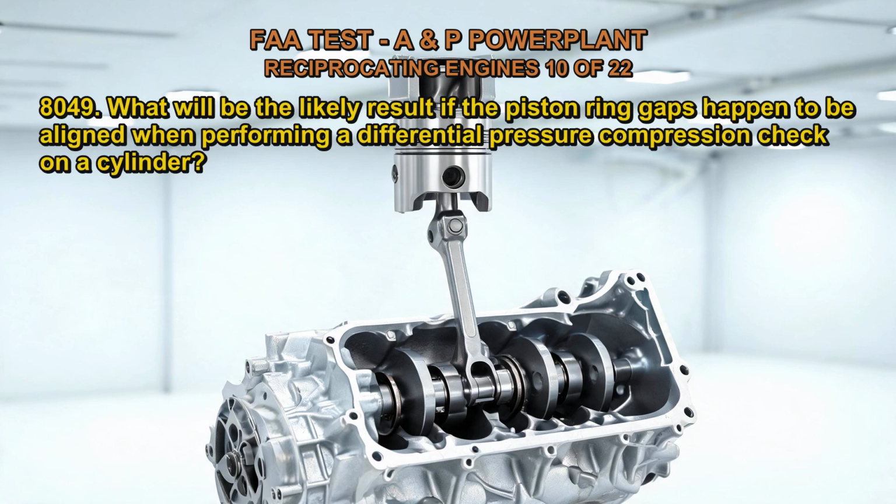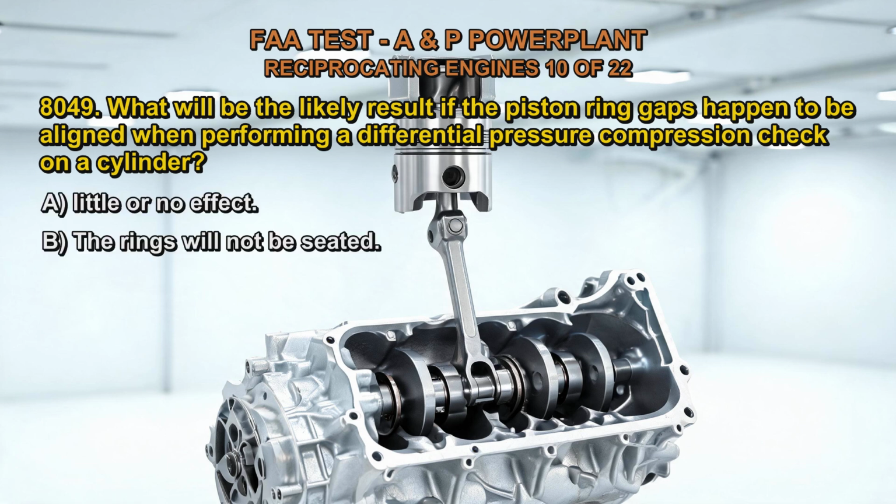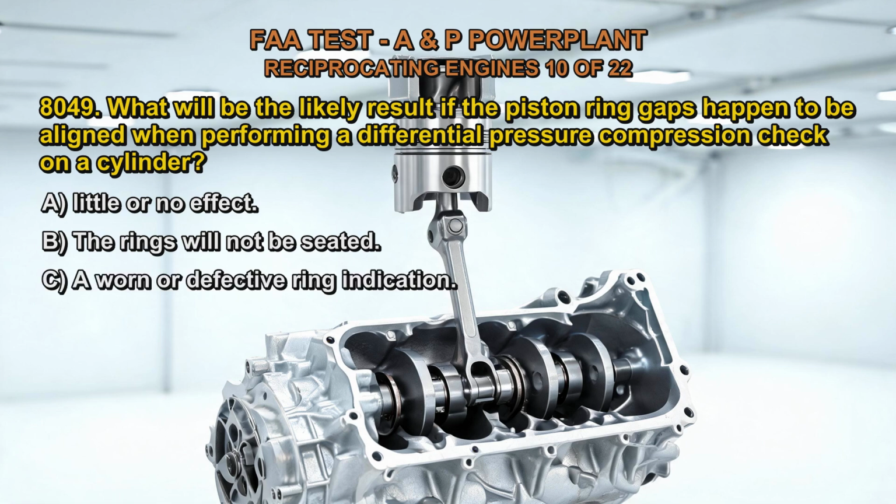8049. What will be the likely result if the piston ring gaps happen to be aligned when performing a differential pressure compression check on a cylinder? A. Little or no effect. B. The rings will not be seated. C. A worn or defective ring indication. The correct answer is C.